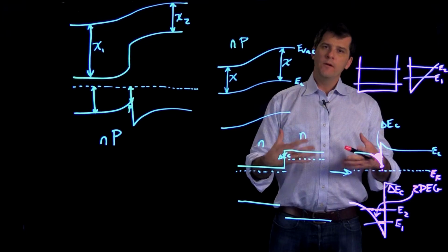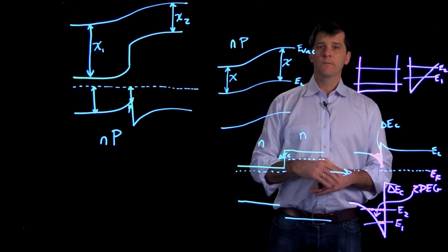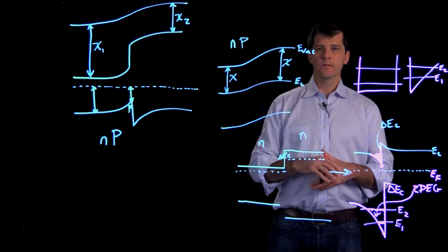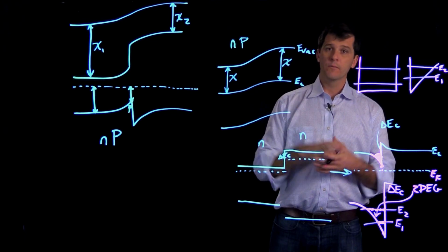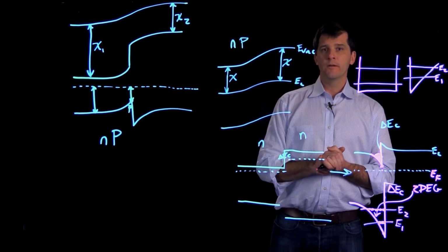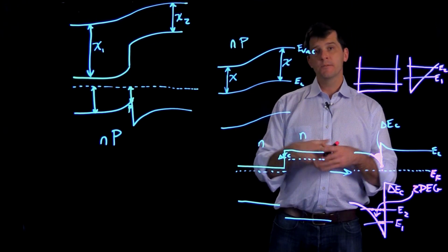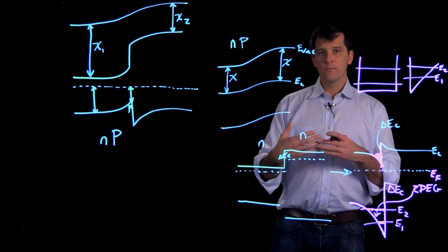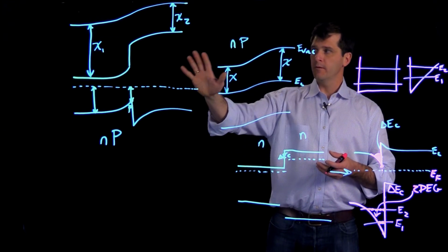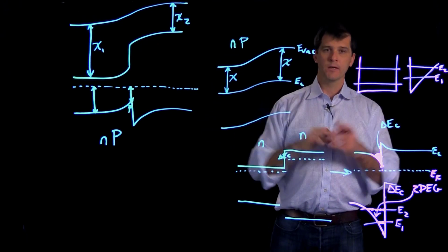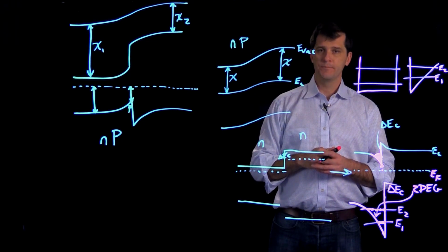So in this section, we've qualitatively described the band diagrams of semiconductor heterojunctions. The expressions for the depletion widths are very similar to those for the normal p-n junction, just with the substitution of the correct dielectric constant for the material 2 or material 1, depending on if you're talking about the n-type or the p-type depletion width.